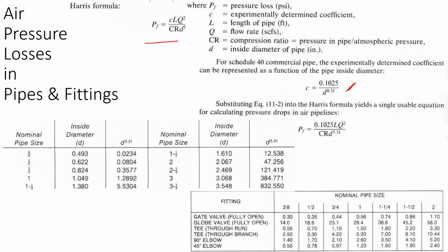Now, the interesting thing about those pipes, you see that nominal dimension, the pipe that says ½ inch, they're not really ½ inch. Their diameter is actually this for a Schedule 40. So when they call nominal pipe size ½ inch, typically that's their internal diameter. However, you see they're not exactly 0.5, they're a little bit off. Anyway, this can be found online or from a textbook, and we need to use this D in the equation, the diameter.